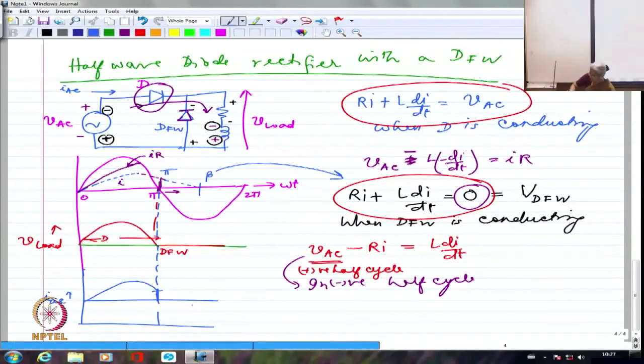You get my point? So, the AC current happens to be different from the load current whenever I have a freewheeling diode. It is definitely going to intervene in the conduction, take away all the current, depriving the supply of any current. It is discontinuous.